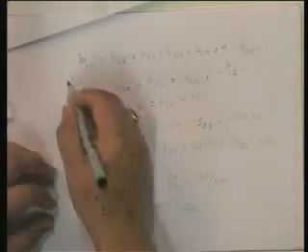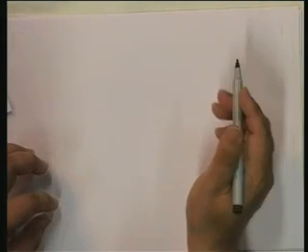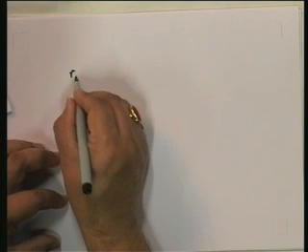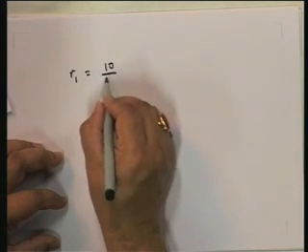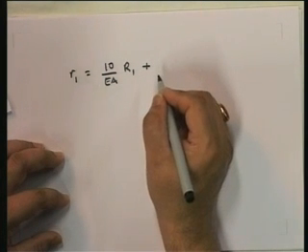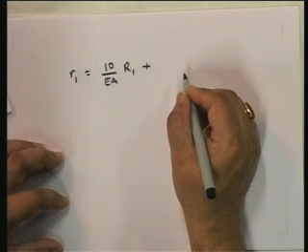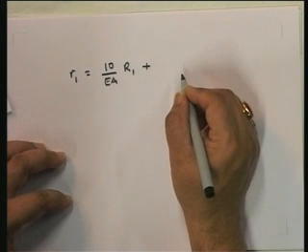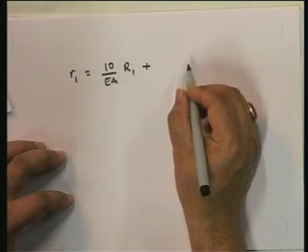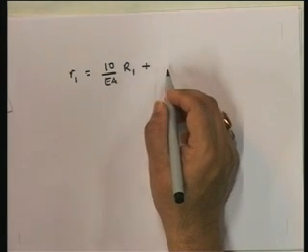If you look at it in BIR, since all the ones are 0 excepting for B4R, you will see that only B4R will contribute. So R1 will become equal to 10 upon EA R1, plus, now if you look at BIR transpose, all are equal to 0, so the only one that will come in will be B4. We need to get B4x, and that is minus 1 over root 2.